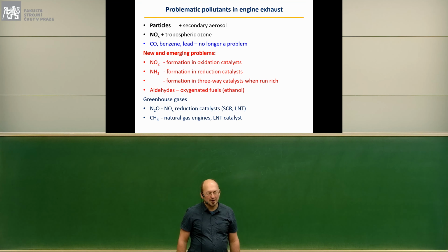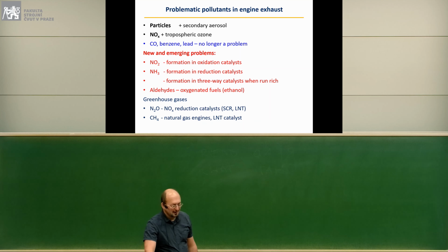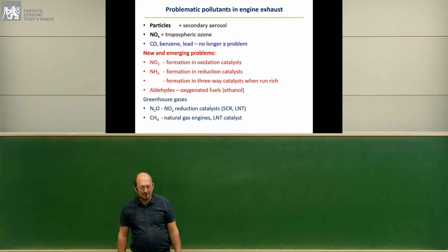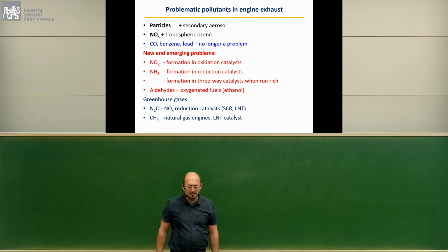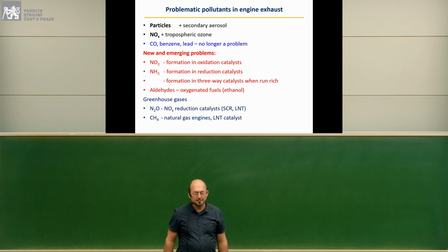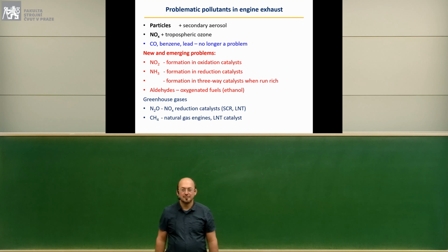These are carbon dioxide originating from fossil fuel combustion, and from transport the two other relevant ones are unburned methane from methane-based fuels, and nitrous oxide N2O, which is primarily produced in certain types of catalytic converter under certain conditions.